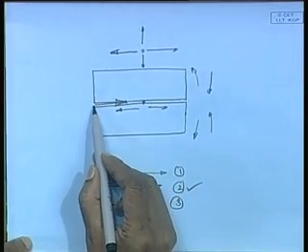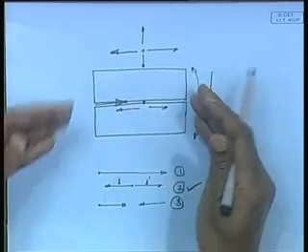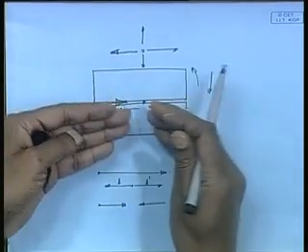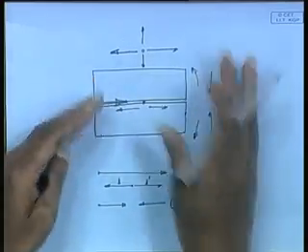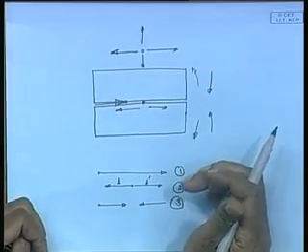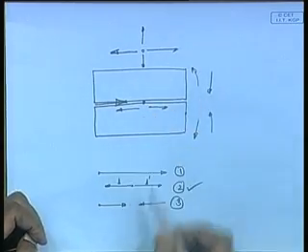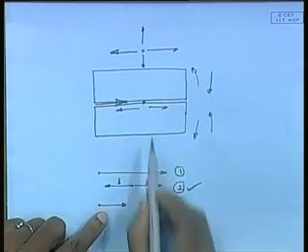Just in this case, if I do welding sequence number 3, what will happen? I start welding from this side and also from this side. The stresses are getting kind of accumulated. In the middle it may get bulged. All right, it is a simple case, but still the ideal is number 2, when I go outside.